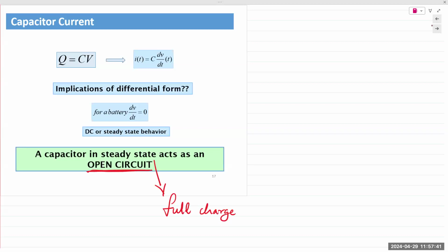Exactly, that's going to be the next point. For an AC circuit, it's constantly changing. So when it changes, the electrons start moving again, constantly, right? So if it's DC, it reaches a full charge, electrons stop flowing, it behaves like an open circuit. Now you change it. If you change the input voltage, electrons will start moving again. Whether it goes higher, whether it goes lower, doesn't matter.